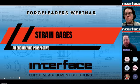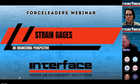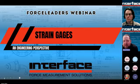Yeah, I just want to add real quick. All of our cables will support 6-wire. So even if the sensor is not a 6-wire or sense-enabled sensor, the cable will allow your instrumentation to actually read what that voltage drop is. And again, this all goes back to the fact that load cells are ratiometric, right? So that cal data is a function of 10-volt excitation, or whatever the voltage is on that cal cert. And oftentimes customers don't realize that it's not quite getting what they think is getting to the sensor.